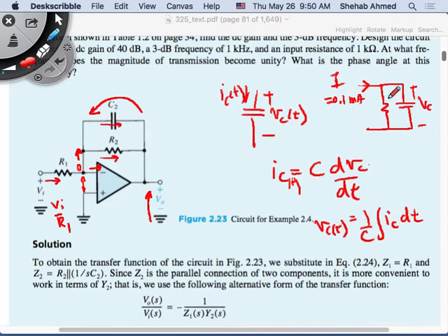Multiply by what? The current? Yeah, but what is the current? Remember, this is the 214 transient analysis stuff: how the capacitor is charged initially or not charged. And then what happens at infinity? What happens if you keep pumping input DC current into a circuit like this? The capacitor becomes an open circuit.